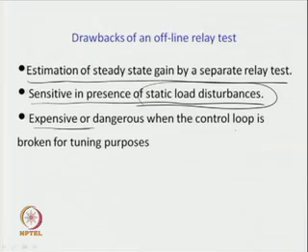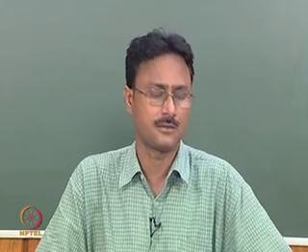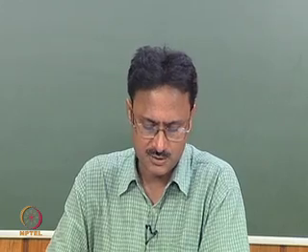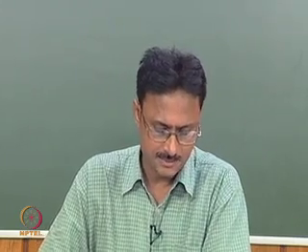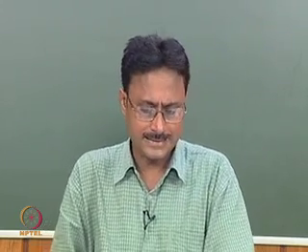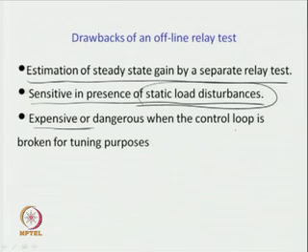For the purpose of PID controller tuning, when the loop is broken, the normal operation of the system gets disrupted, which is not desirable for many real time systems. Rather, it is often desirable to tune the controller under tight continuous closed loop operation.